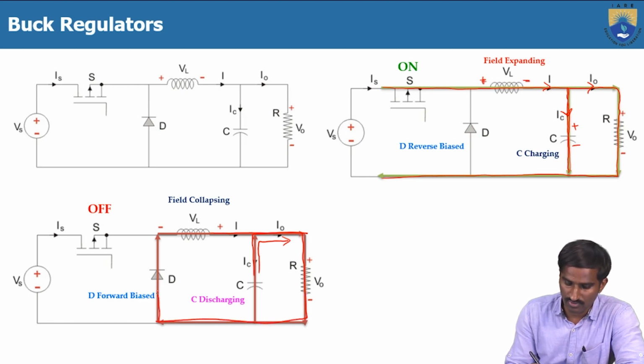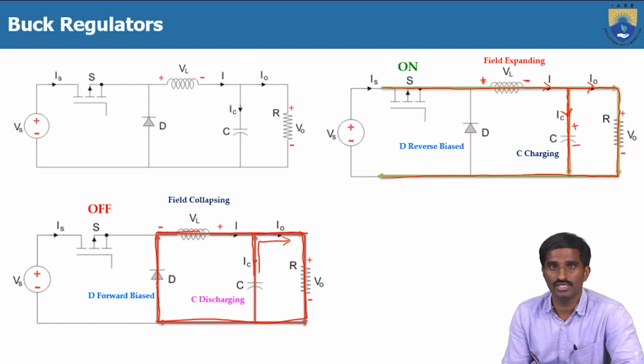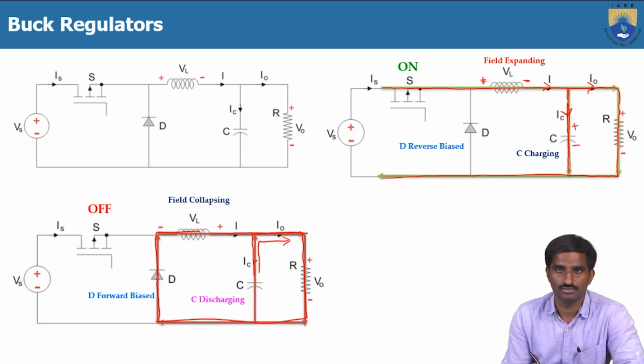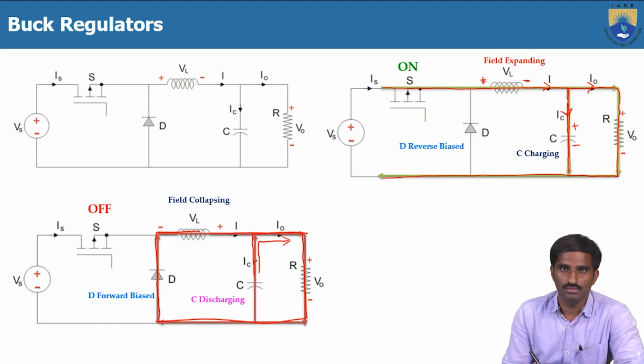Then this time the diode will get into the forward bias, because here the switch is turned off. So there is no way to close this loop. That's why then the load current will flow through this diode, then the diode will get into the forward bias. Same principle like the buck converter or the step down converter.